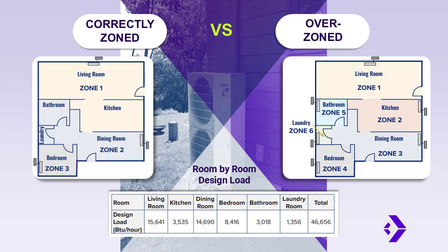The reasoning here wasn't just convenience or usage, it really came down to thermal conductivity and load balancing. Those rooms share walls and doorways, so heat naturally transfers between them. By grouping these spaces together, we hit this kind of sweet spot. The system serving each zone is big enough to stay within its modulating range, but not so large that it's constantly cycling on and off.